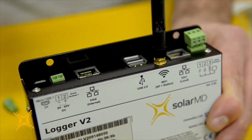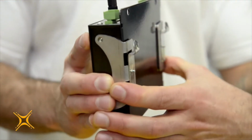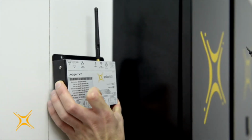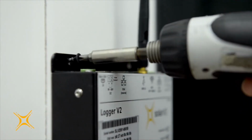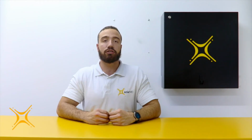Step 3. Mounting instructions. The logger has pre-drilled holes for easy mounting. A DIN rail mounting kit is optional. For reliable operation, it is required that the data logger be located within 100 meters of an Ethernet connection and within 10 meters of the CAN bus connection.